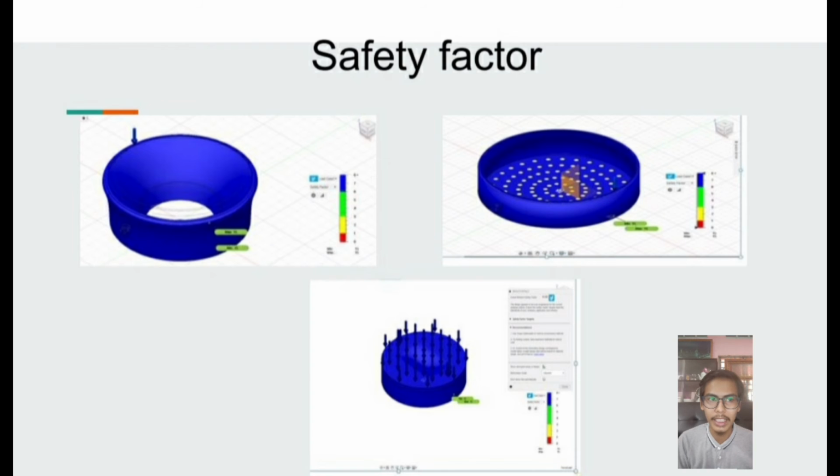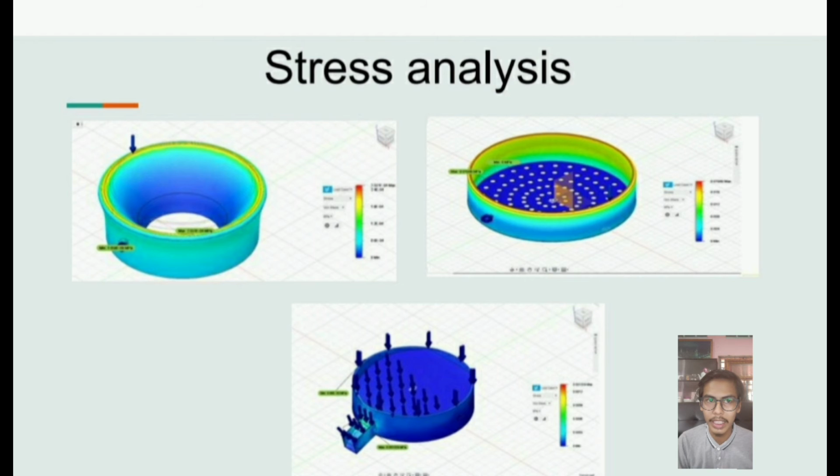For ductile materials, it is often required that the factors of safety be checked against both yield and ultimate strength. The yield calculation will determine the safety factor until the part starts to deform plastically. The ultimate calculation will determine the safety factor until failure. On brittle materials, these failures are often so close as to be indistinguishable, so it is usually acceptable to only calculate the ultimate safety factor.